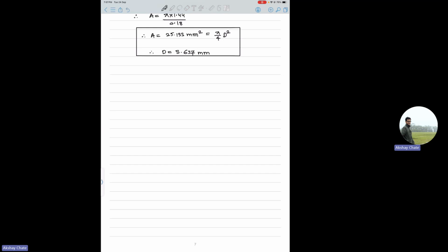And your workpiece moves, or if your workpiece is steady, your electrode or the welding tool moves in one direction. But when you study welding processes, you assume the electrode to be stationary and your workpiece moving in the negative direction. So basically you do a change of frame of reference.